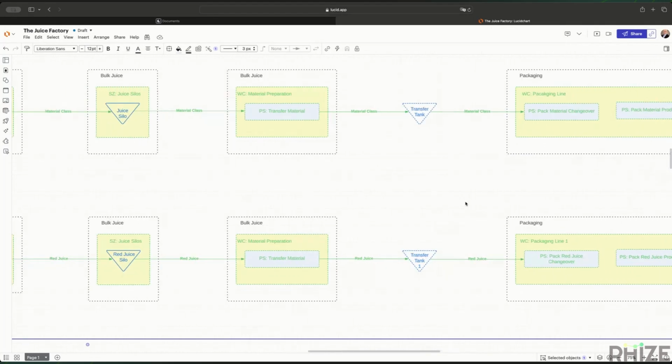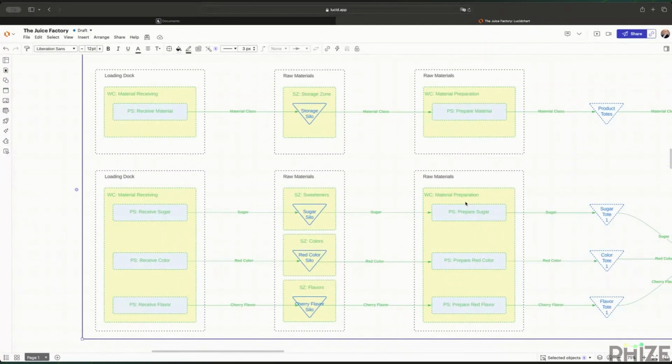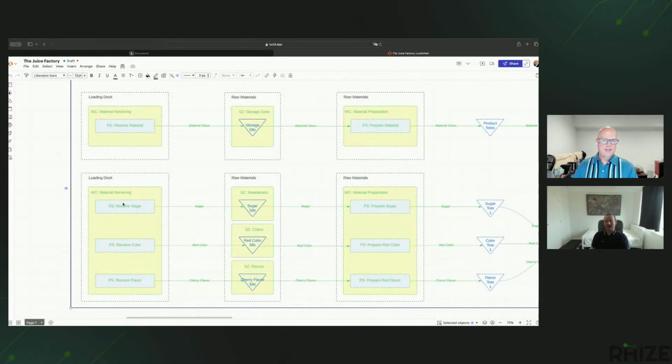So what this is doing is it's mapping out the exact process of what are all the areas where work occurs, what are all the process segments that need to be created with that. And what we would also have in this case are all the materials, all the assets that might be associated with that. If there's, say, a specific mixer impeller on this mixing tank, or the number of operators that are associated with that, all of those resource models will be included in that particular process segment as we really get into the weeds of that. So far so good, Tom?